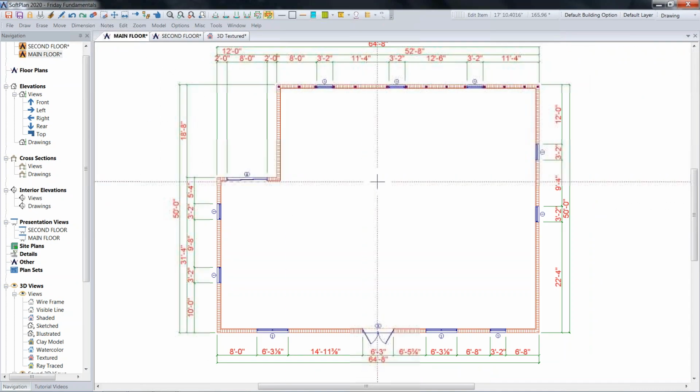Now, real quick, I'm going to come in here and put a set of stairs in here, and then I'm going to make those stairs reach automatically for the second floor. Automatically. Here's the stipulation for new users. If you intend to put a set of stairs into your drawings, you must have already defined both floors, number one. Number two, they have to be modeled together.